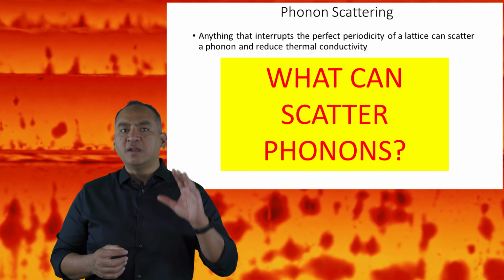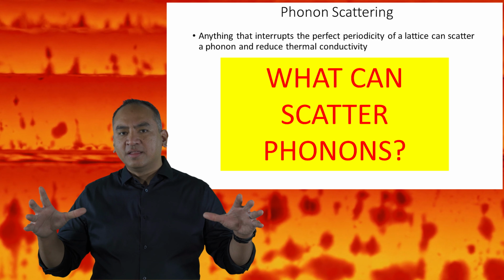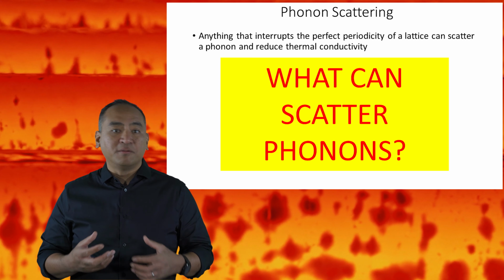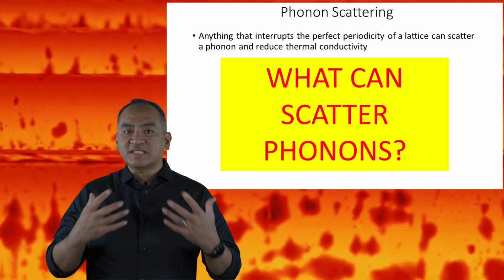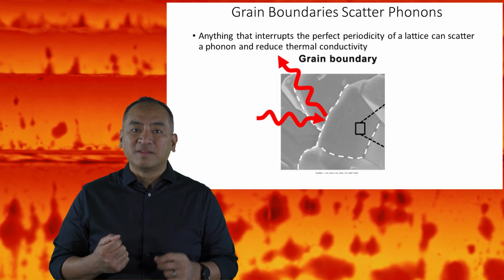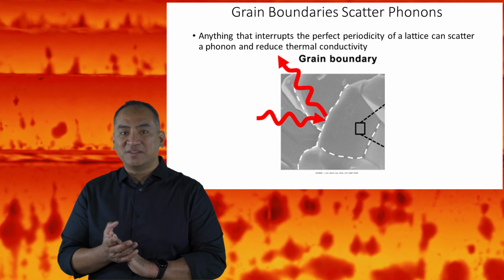Let's first focus on phonons. Anything that interrupts the perfect periodicity of a crystal lattice can scatter a phonon and reduce thermal conductivity. So, what can scatter lattice vibrations in a solid material? Grain boundaries can certainly scatter phonons and reduce thermal conductivity.